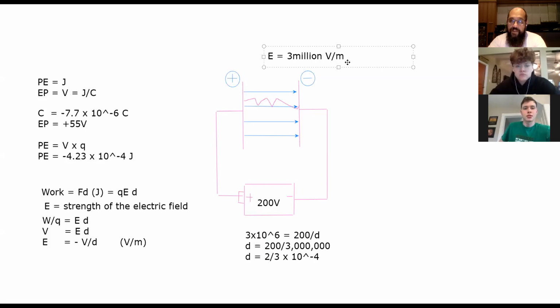If you put something like glass, or even paper, it will do a better job than air. Those are materials known as dielectrics. Putting dielectric materials between the two plates will enable you to have the capacitor plates closer together without a discharge happening. Okay?